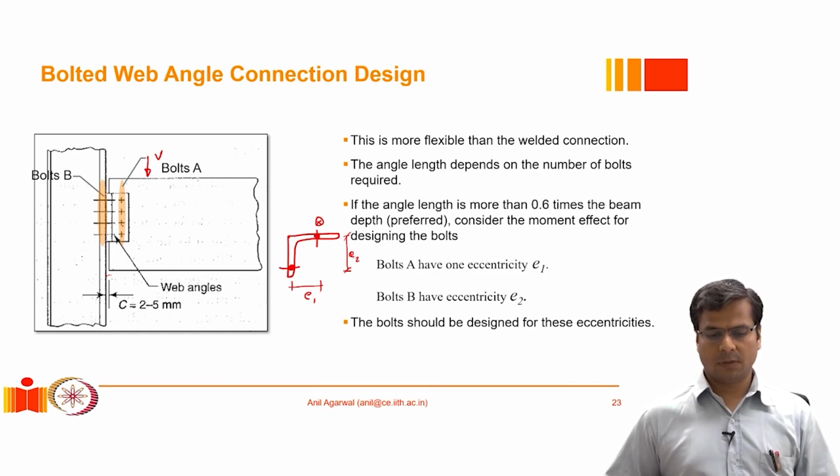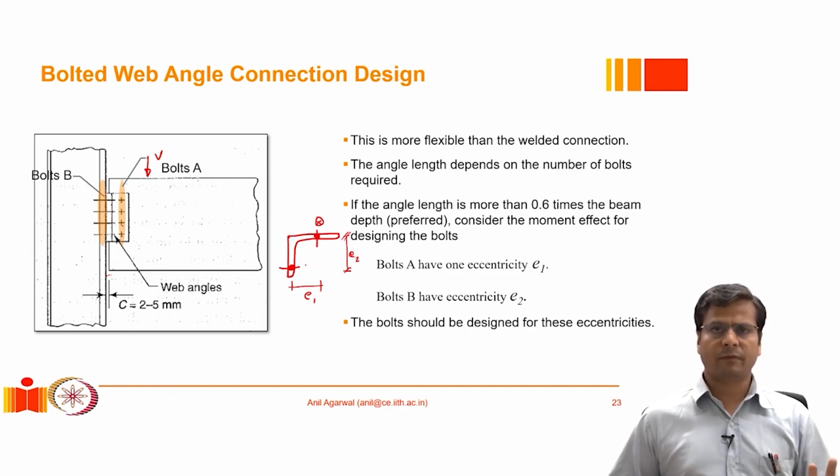And to be on the conservative side, it is okay to design it for this eccentricity. But again, if the eccentricity is within 50 to 75 millimeters, we can ignore it.